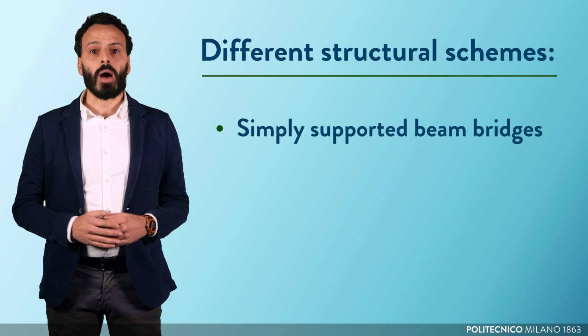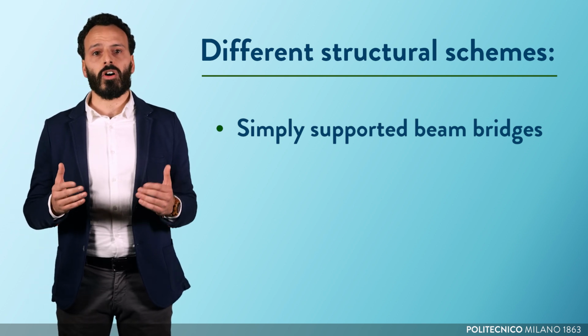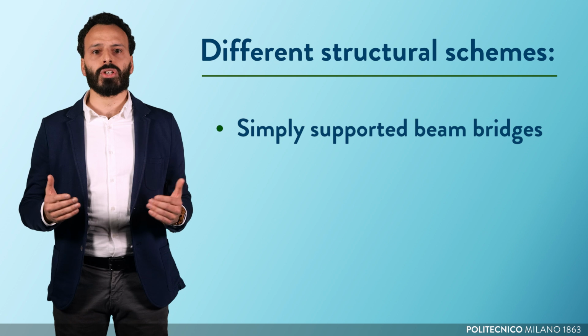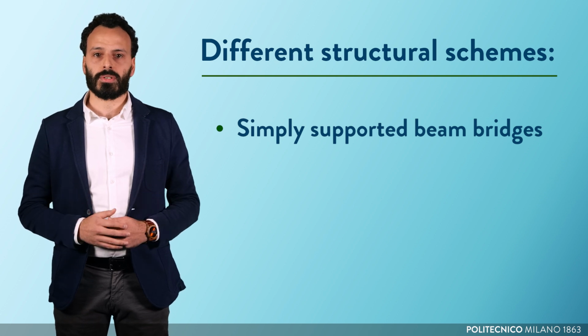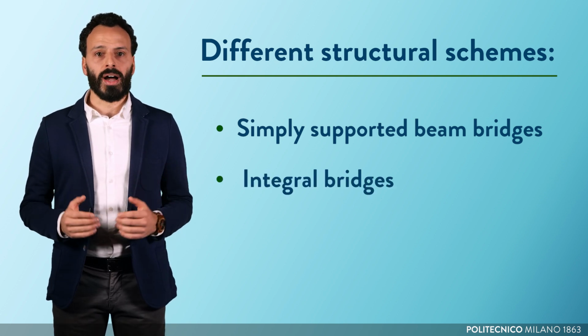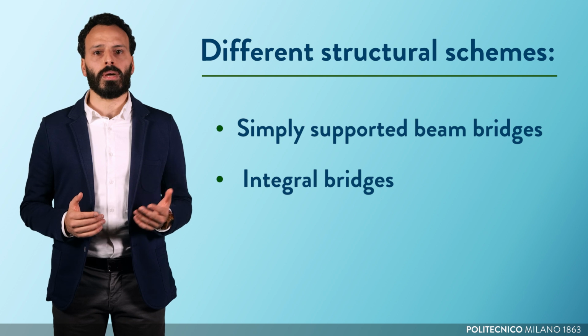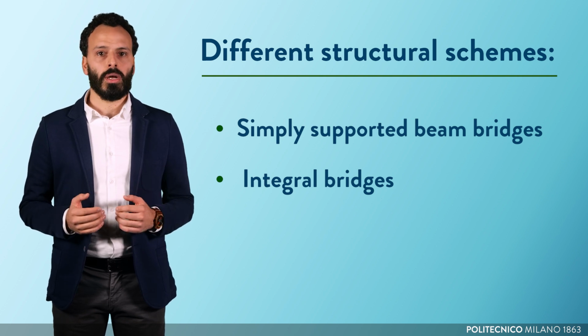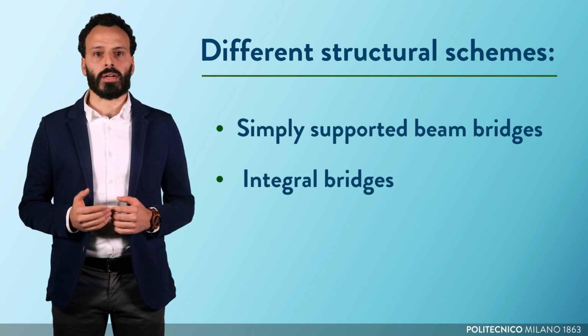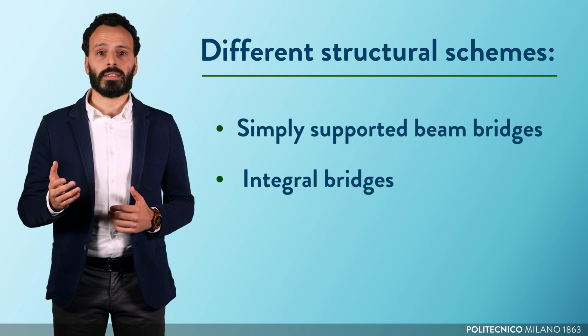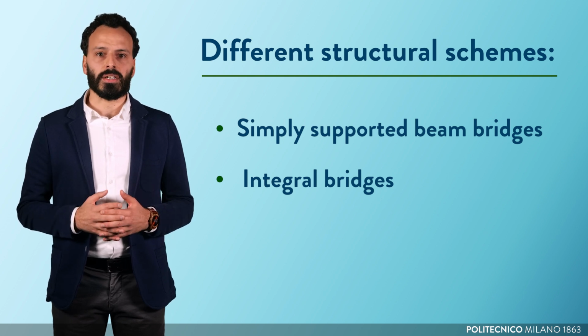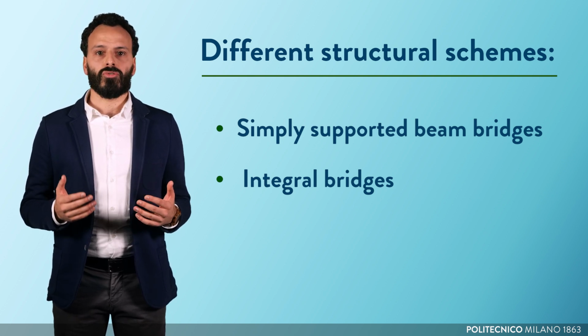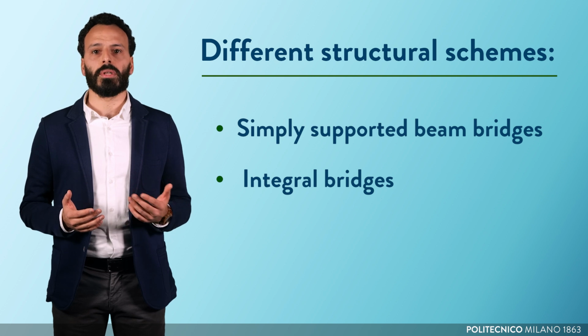However, they can increase the risk of bank erosion, needing larger abutments and protection measures. Integral bridges provide better resistance to environmental risks such as floods, due to the monolithic pier-to-deck connection. Nevertheless, this alternative significantly increases construction complexity, representing an insurmountable limit.